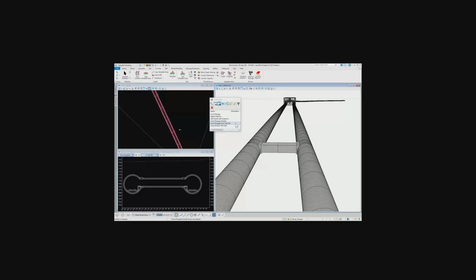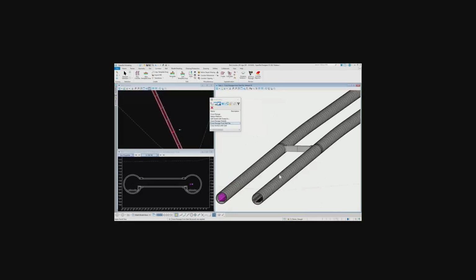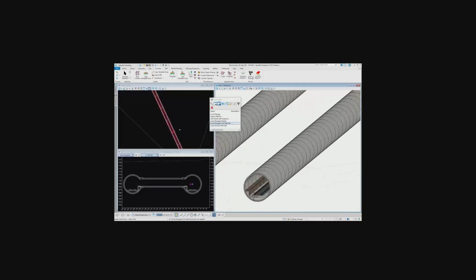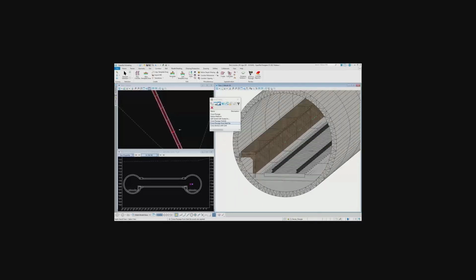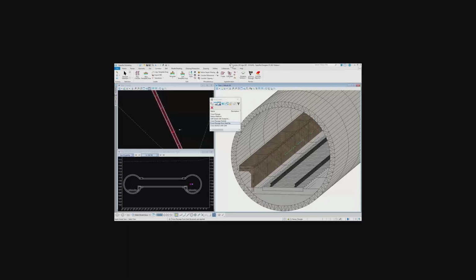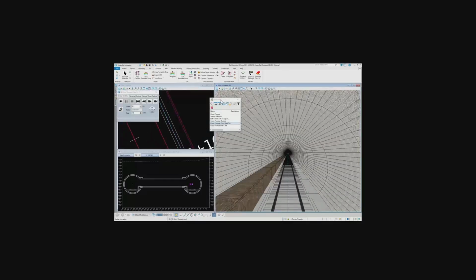Like for instance, in this case, you can save views as you do in your normal CAD software, because OpenRail has MicroStation as well. And then we have this review tool, specifically the 3D drive-through tool that allows you to visually inspect the model that you have designed.